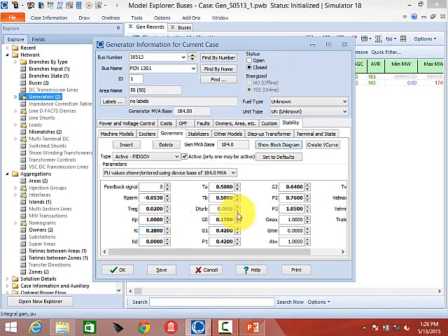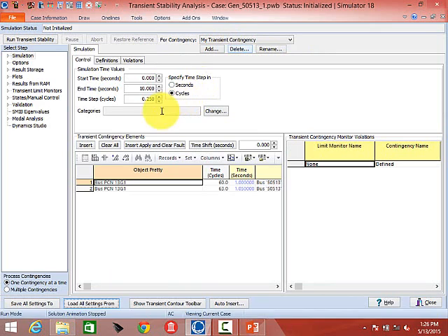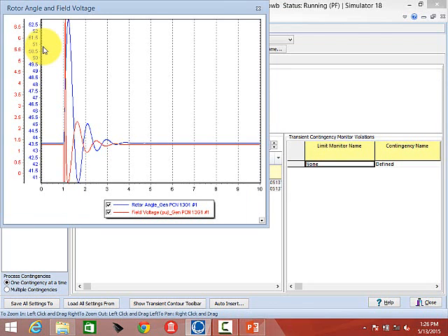Because we've got a little case here, we're going to run transient stability, and when it creates a two-bus equivalent, it automatically puts in a little fault for you, which is just fault the bus for a 20th of a second and then clear it. So go ahead and run that transient stability run, and you look at that response, and you think, oh, not a problem, that looks fine. Everybody get it? Fine.